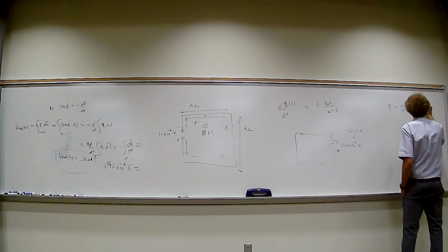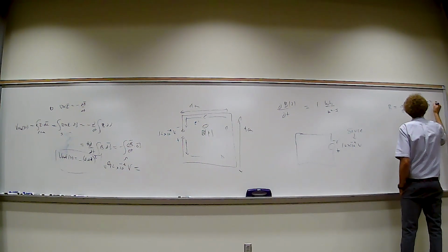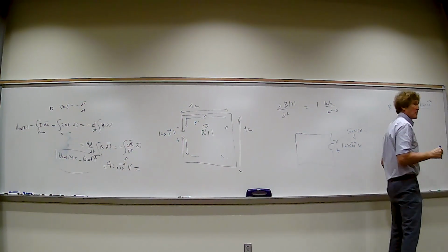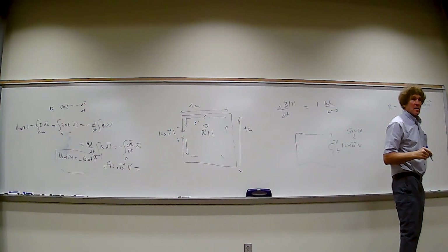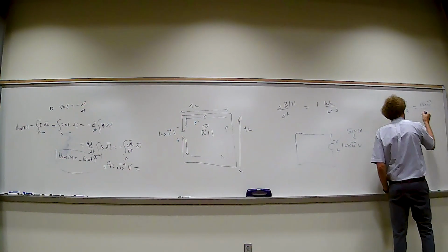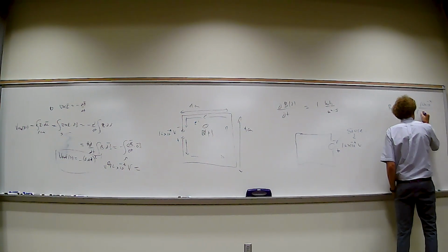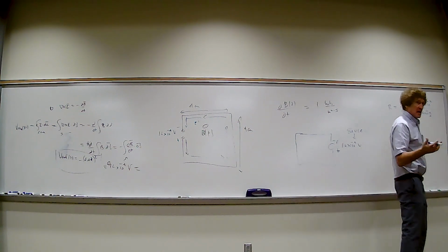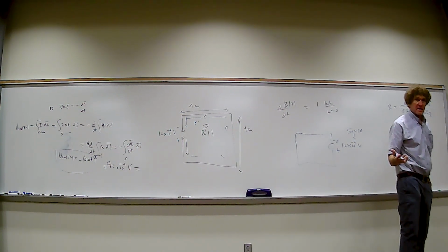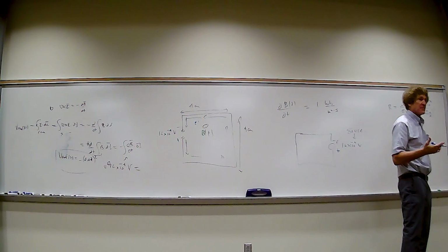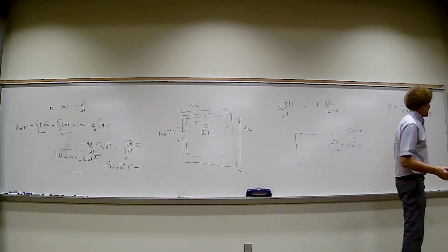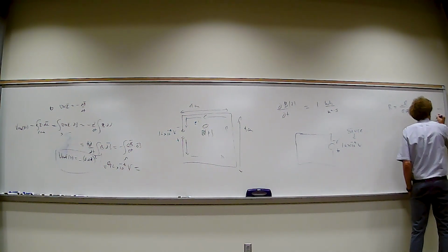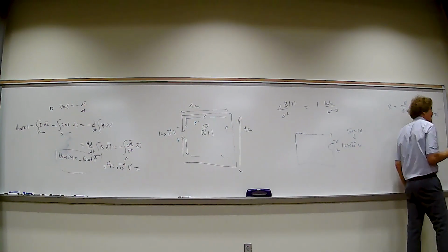So L is going to be 16 times 10 to the minus 2. Is this copper wire? Yeah. All right, so for copper, the conductivity is 5.8 times 10 to the 7th. And the units would be Siemens per meter, but I'm going to just leave it like that. Y'all with me, class? You understand that? That's the conductivity, 1 over the resistivity. In physics, they use resistivity. Then it's times the area. And the area would be pi radius squared.